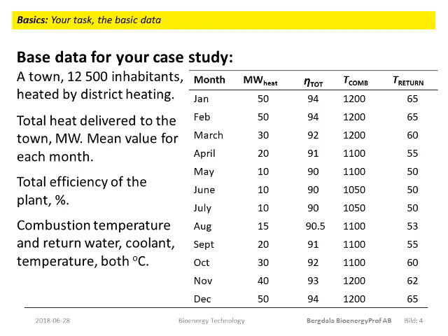The load on the district heating system varies across the year, with a maximum at 50 megawatts in December, January and February, while in May, June and July it has a minimum at 10 megawatt, and then it changes during the other months. The water coming back from the district heating system, the return water, is used to cool the exhaust steam from the turbine in the electricity production.